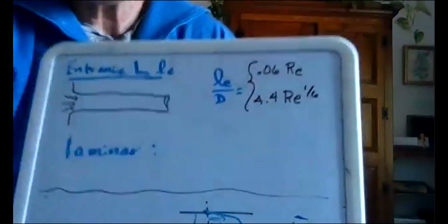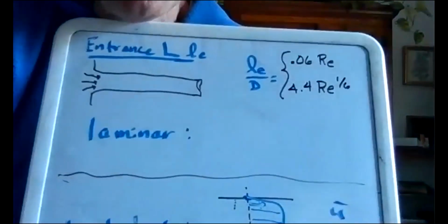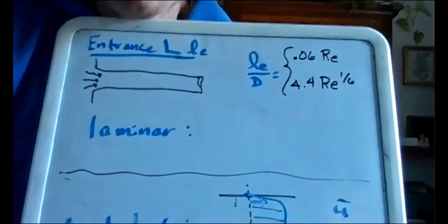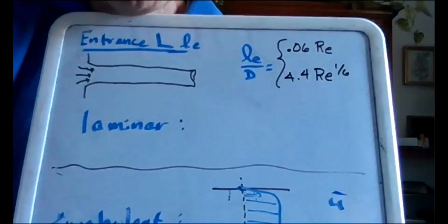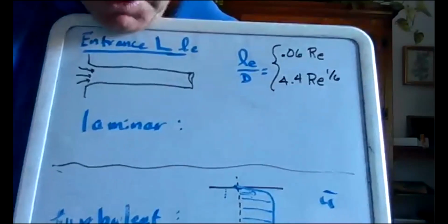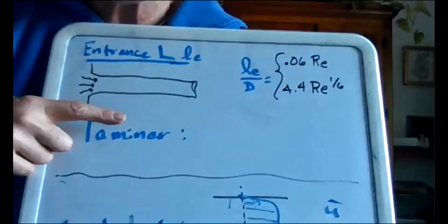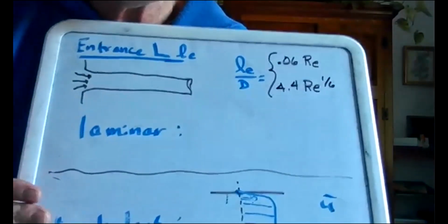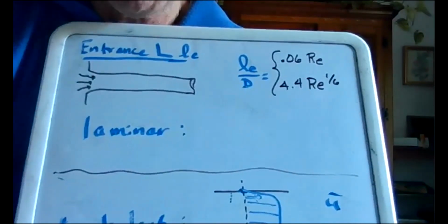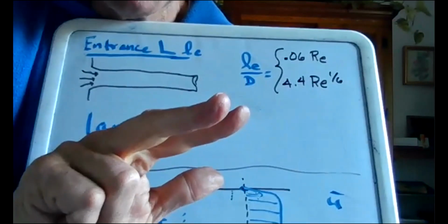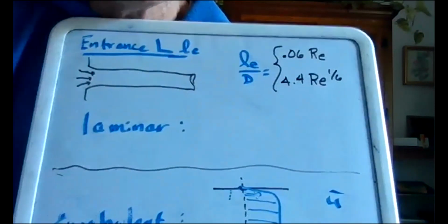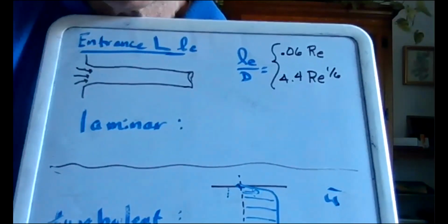All right, the last preliminary thing to do before getting going on that fundamental calculation, which is, how much friction are we talking about for our piping system, is to get the entrance length. So we've got some fluid entering a piping system, and eventually it's going to settle into one of the 3-4 flow regimes: laminar, transitional, turbulent, or maybe inviscid if that's a reasonable assumption.